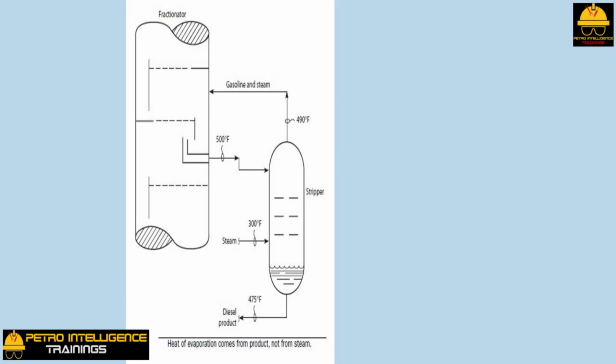Example calculations. For example, if we have 101 pounds of soup in a rather large bowl, and cause 1 pound to evaporate by blowing across the bowl, the soup will lose 1000 BTU. This heat of evaporation will come at the expense of the temperature of the remaining soup in the bowl, that is, each pound of soup will lose 10 BTU. If the specific heat of our soup is 1.0 BTU per pound degree F, the soup will cool off by 10 degrees Fahrenheit. A steam stripper, as shown in picture, works in the same way.